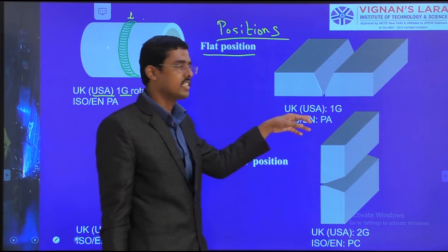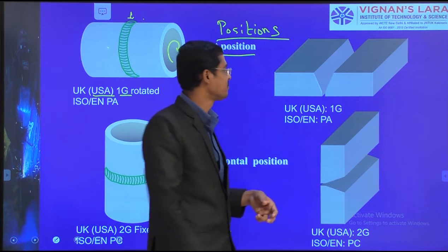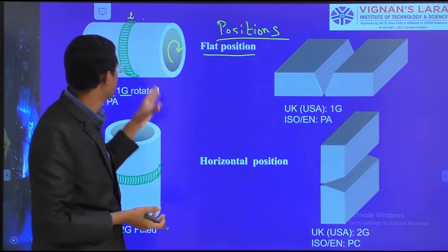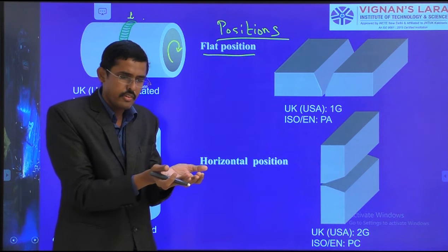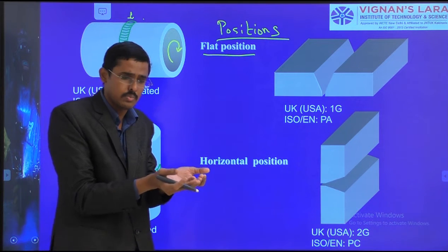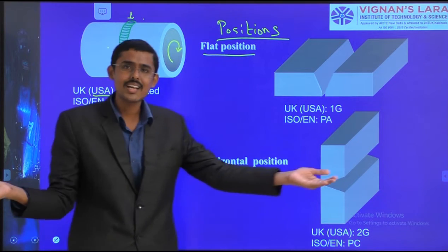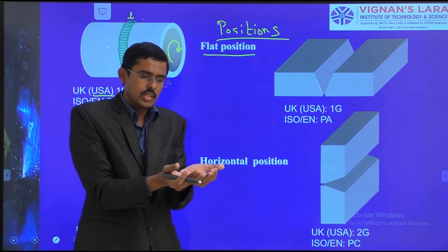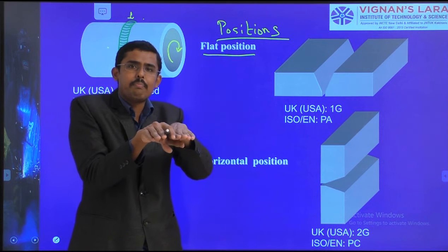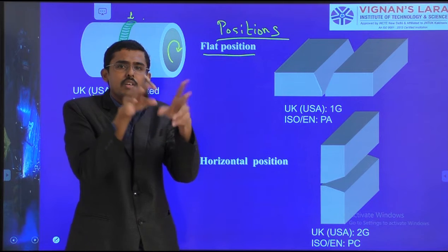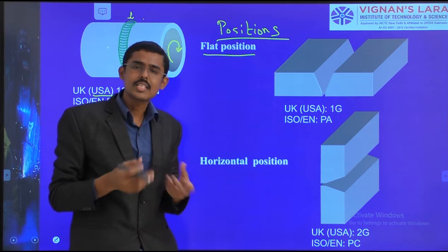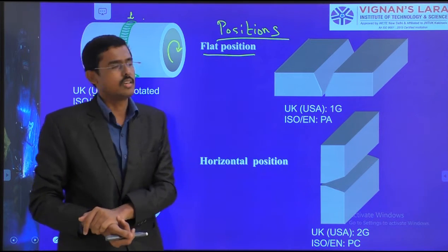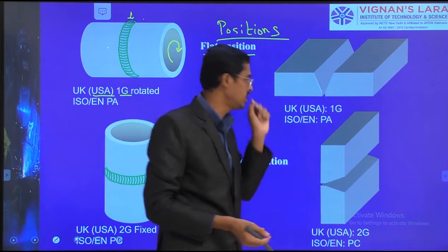Similarly, instead of a pipe I may have a plate. There are two combinations: maybe a pipe, maybe a plate. During the casting process we manufacture plates and bars, and those all come under plate. If not a plate, it can be a pipe. We bend and make pipes for boiler plants. So we qualify the welder with respect to these categories.